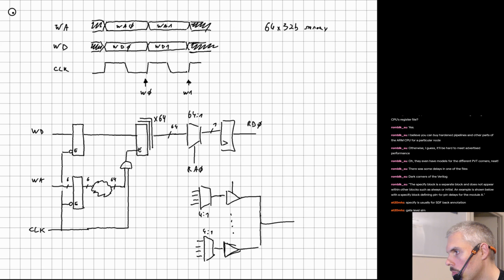Why this sort of mixed architecture between a real mux and a buffer is that to drive this line, which might be long and potentially have high capacitance, I would use a fairly big drive gate, something like underscore 8 or underscore 16 size gate, to be able to drive that line quickly.